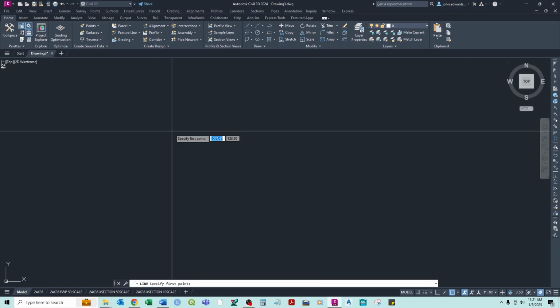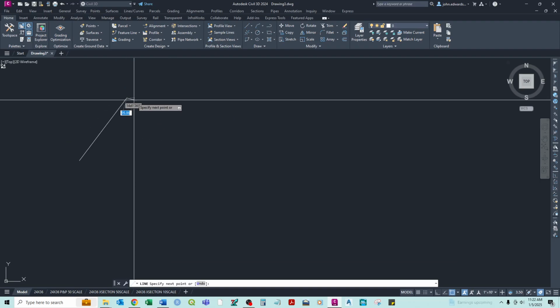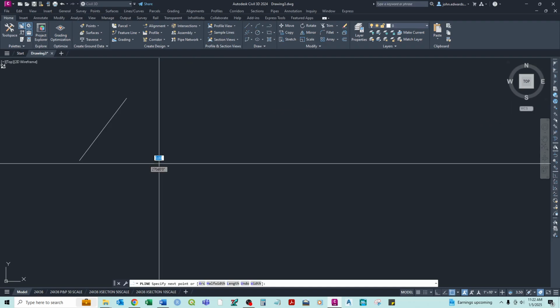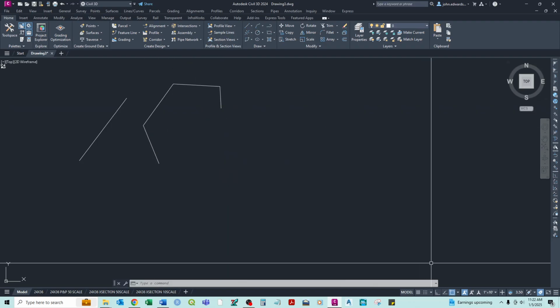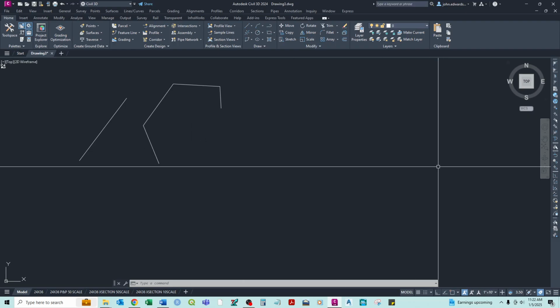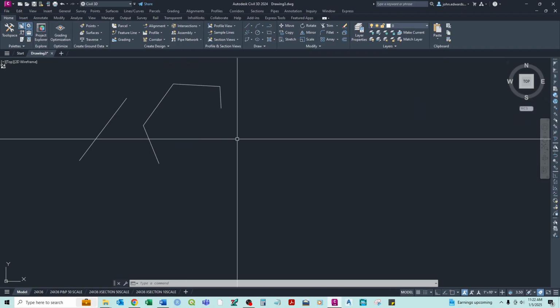So just to start out here, we've done lines, which L is our keyboard shortcut. We've done polylines, which PL is our keyboard shortcut. I'm going to turn snapping off. We have learned about ortho mode, and we've learned about snapping so far. But so far we've basically only done these straight lines. So in thinking about lines, now we have learned ways to draw a closed polygon using